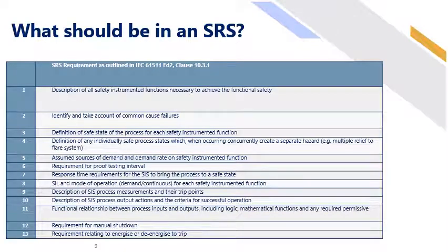The first thing that IEC 61511 addresses in the life cycle is the safety requirements specification. Now, the SRS is a document that outlines the detail of how safety functions are going to be applied. Some of the requirements can be generic to the safety instrument system, but a lot of them are specific to the actual SIF itself. As mentioned previously, it's kind of like an instrument data sheet, but for the whole function.